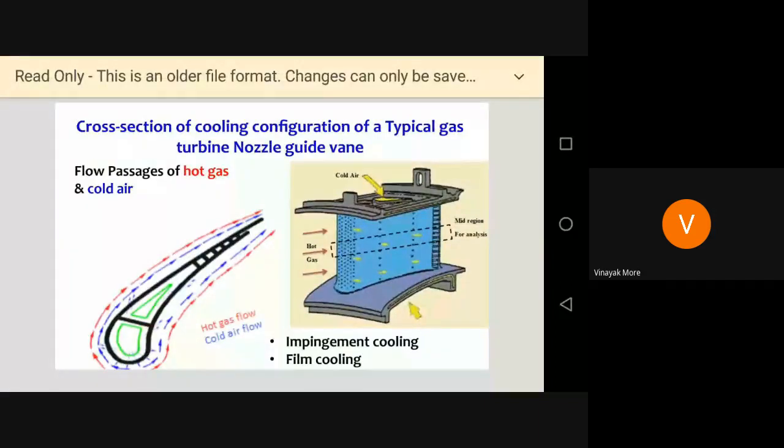Here you can see how the film cooling is done. Earlier you have seen that with the inserts we have the impingement cooling, and pin fins are connected for increasing the surface area, and ducts which are internal or the rib passages. But here, once the impingement holes are supplying the cold air from the inside, that air movement is going to prepare some film on the surface, and this film is going to try to mix with the hot air, or not mix with the hot air, whatever. But this cold air is going to prepare some thin film, or a cold surface, on the blades. So this will help us to maintain the turbine temperature at lower conditions.